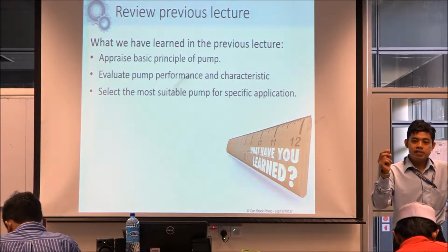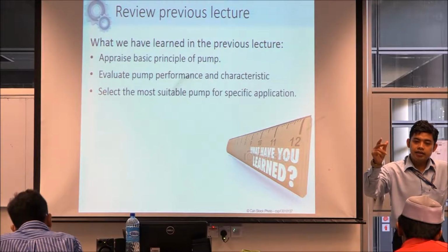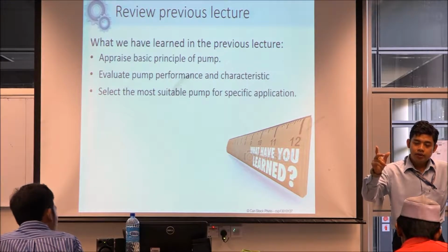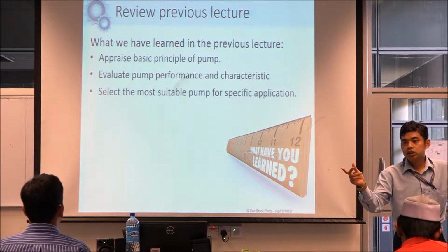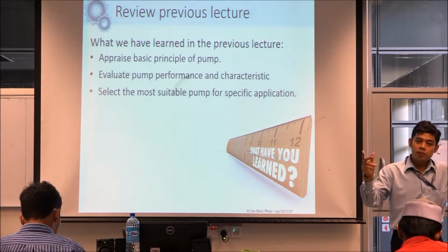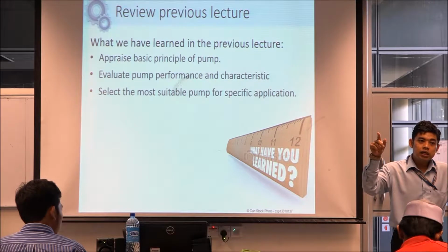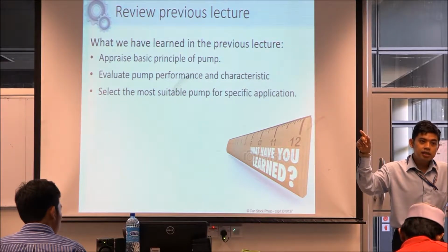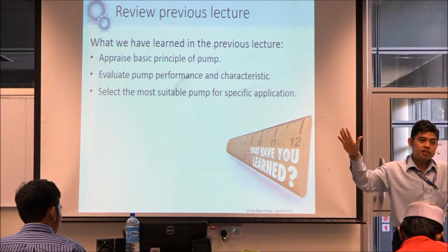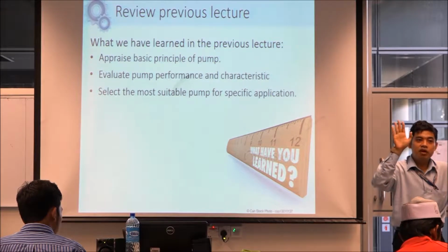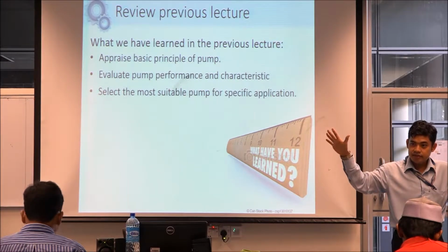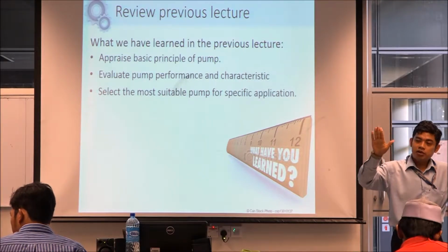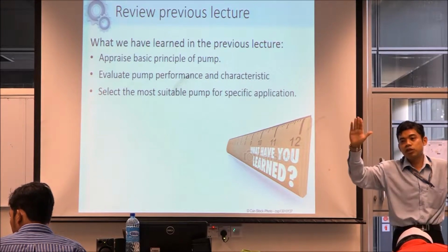It can be twisted, right? It can be twisted, rather than asking you about the Q, asking you about the power, because the water horsepower is Q times delta H times gamma. Gamma is constant and delta H is a function of Q, right? Once you get your Q, you can calculate HS or HP, because Q is at HS equal to HP.